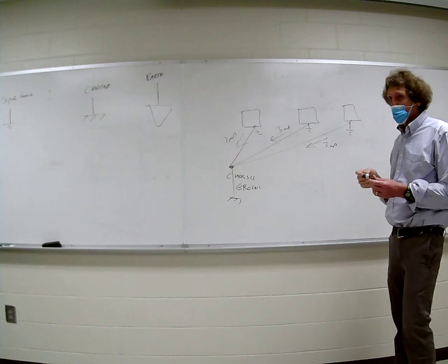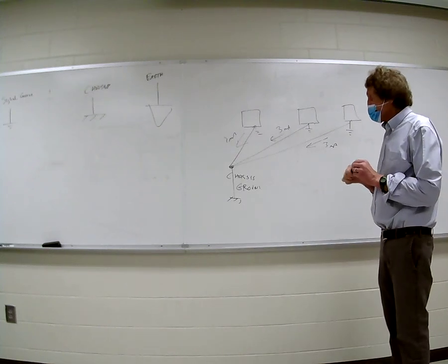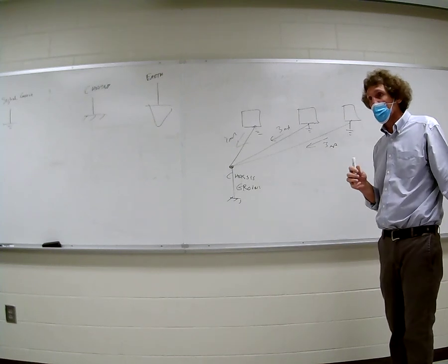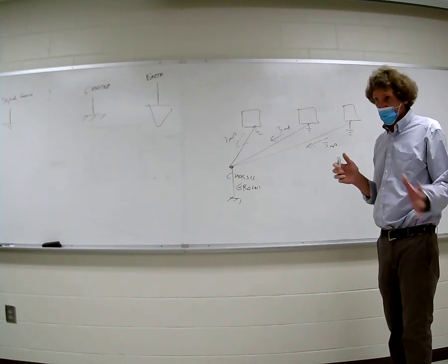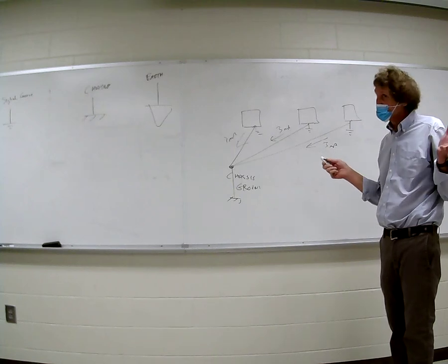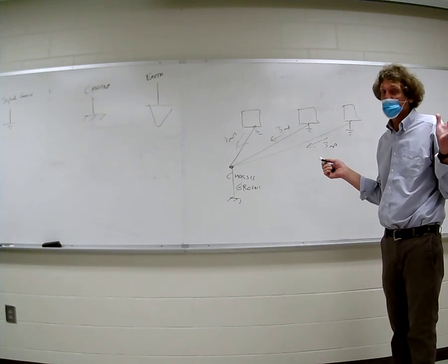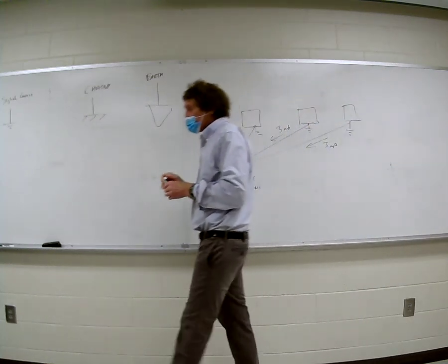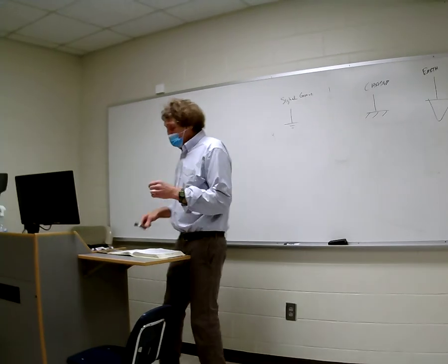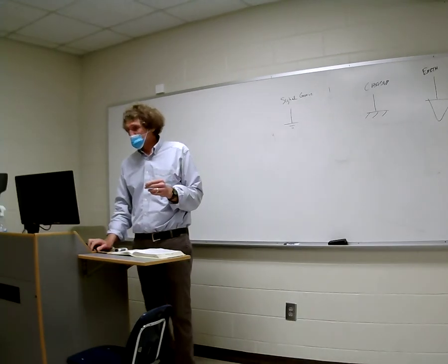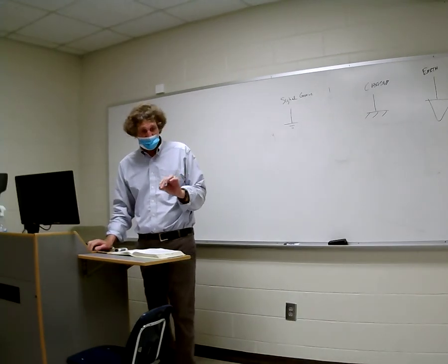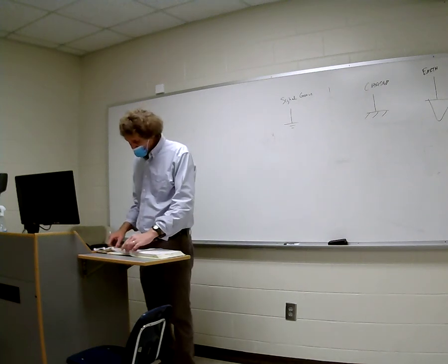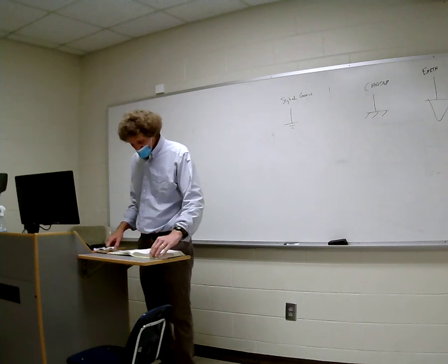Now, chassis grounds are used a lot of times to make sure that you have some common way for current to get out that's not going to go through a path that's somewhat dangerous. That's another thing. But chassis grounds just mean that. They're the chassis of the device. From a chassis ground to an earth ground, it depends on the application. But generally speaking, the chassis ground would be going through the shortest possible length of wire to get to the earth ground. Now I've got to show you a few things that cause problems.